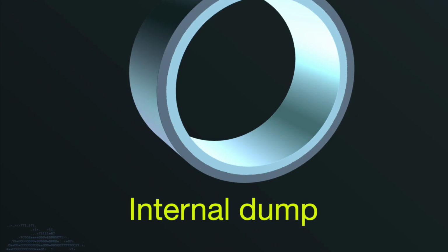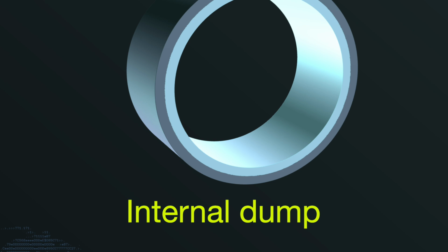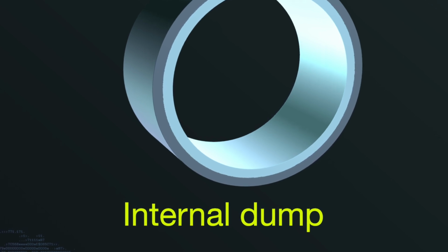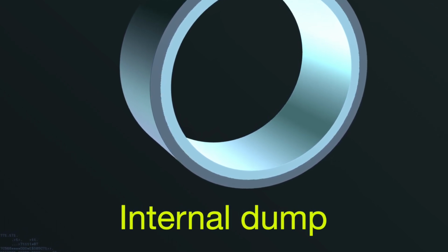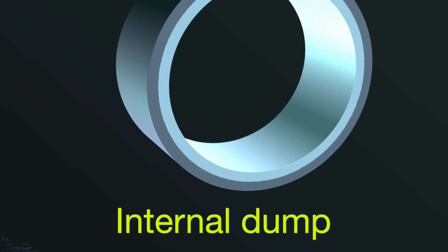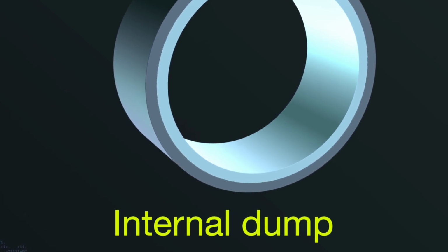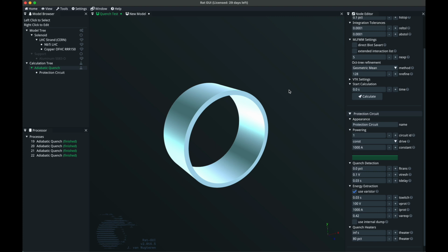Another quench protection method is by not dumping the energy outside the coil in a dump resistor, but by dumping the energy internally. And in that case, we have another checkbox here saying use internal dump.